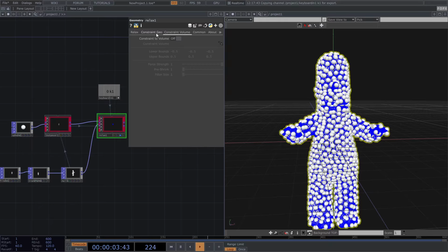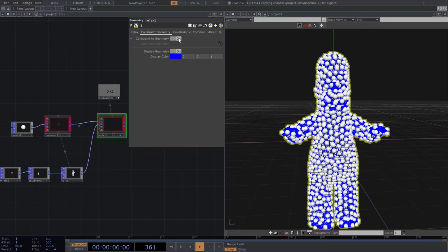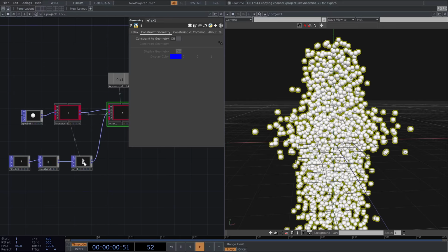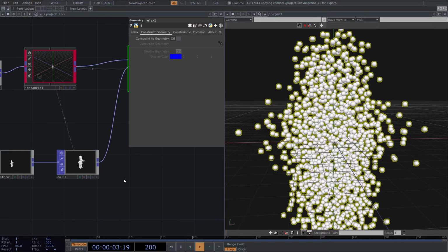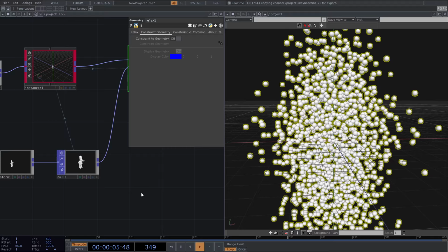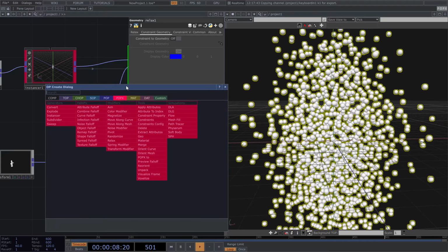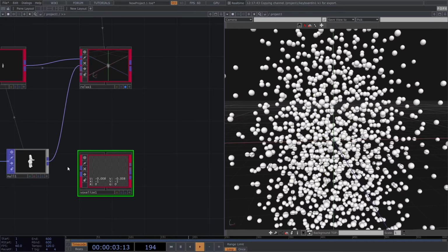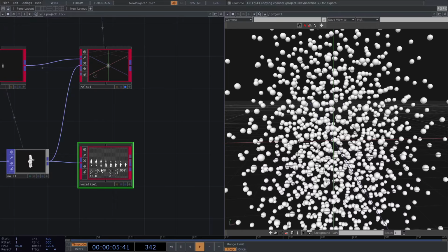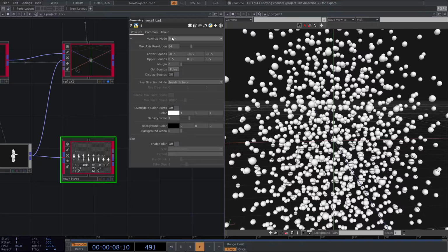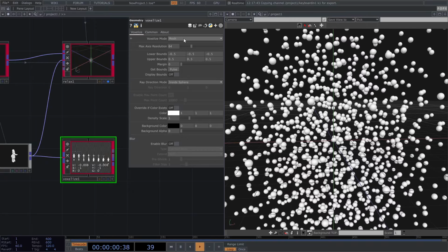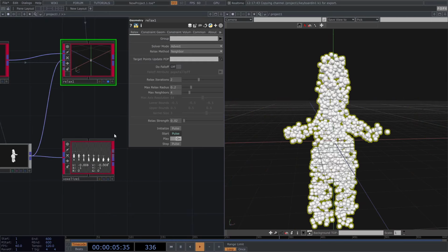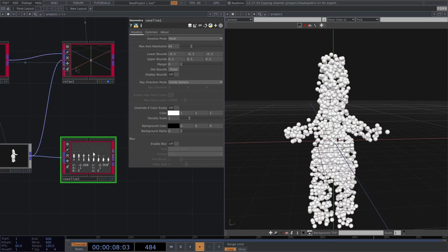So let's toggle off the constraint to geometry. And now I want to basically convert the geometry into a volume, which is going to be represented by a 3D texture. For that, I'm going to use the Voxelize tool and connect my mesh into it. Now the Voxelize tool can voxelize a mesh or point cloud. Currently we want to voxelize a mesh. Let me just init our simulation so it won't interfere.